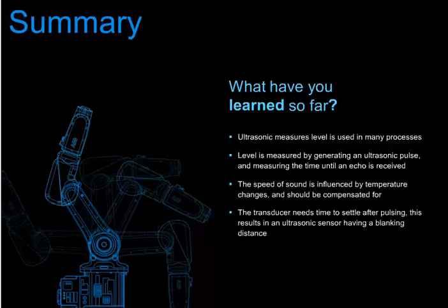Every ultrasonic transducer needs time to settle after pulsing. This results in an ultrasonic sensor having a blanking distance. Ultrasonic sensors have a beam angle that needs to be considered during installation.